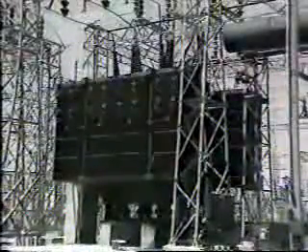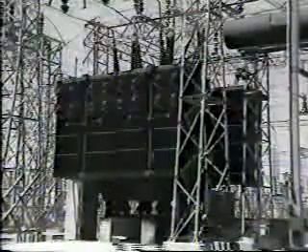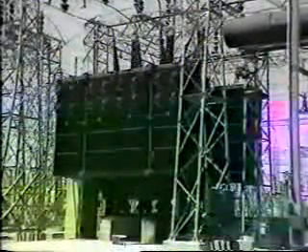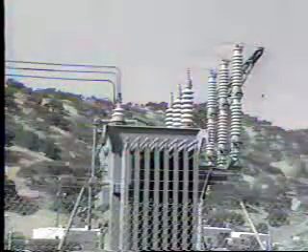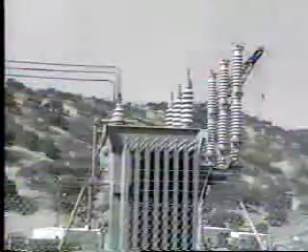Transformers are used all over the power system at all voltage levels and in sizes ranging from, say, 3 kVA up to 500 MVA. Generally, power transformers are three-phase. That is, the primary and secondary windings of each phase are wound on three legs of a common iron core, all immersed in the same tank of insulating oil. Single-phase transformers are also used, connected to form a three-phase bank.